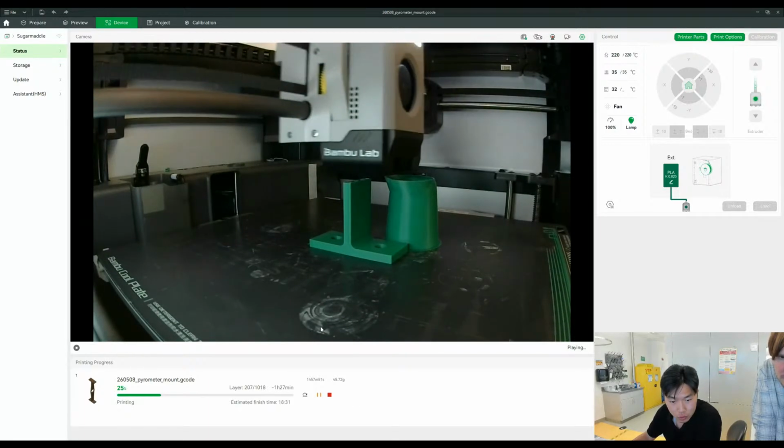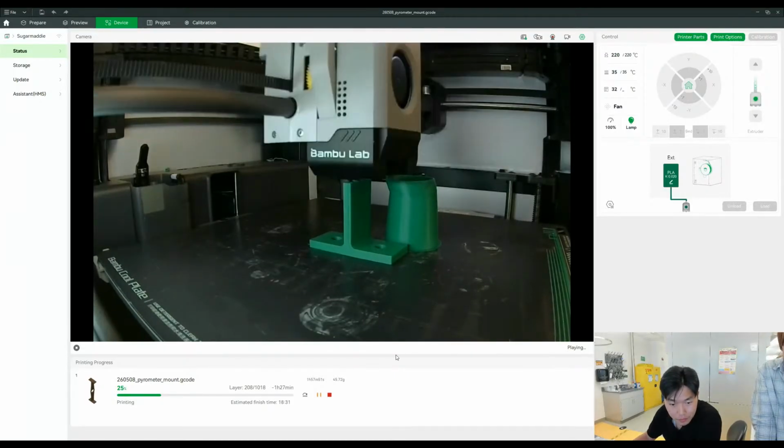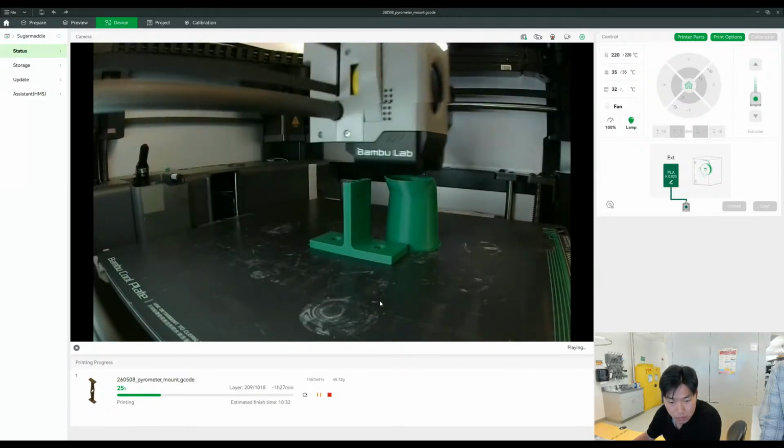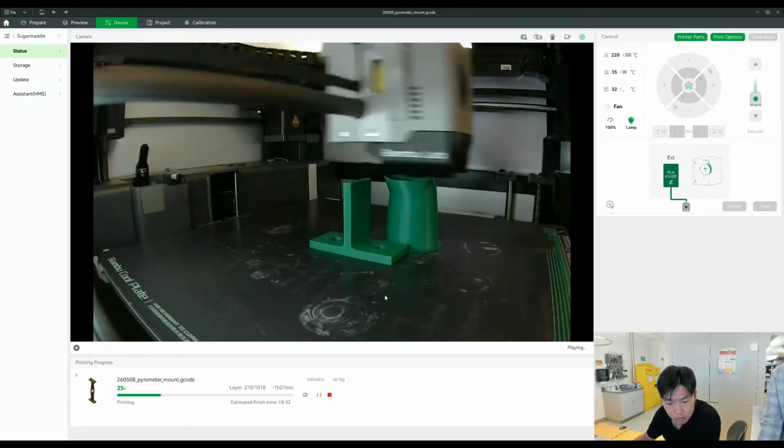Okay, so how do you control it? If it's a 0 to 10 volt input, it's probably proportional, on a scale of 0 to 10. If you send it 5 volts, it's probably doing 50%. If you send it 10 volts, it's doing 100%.